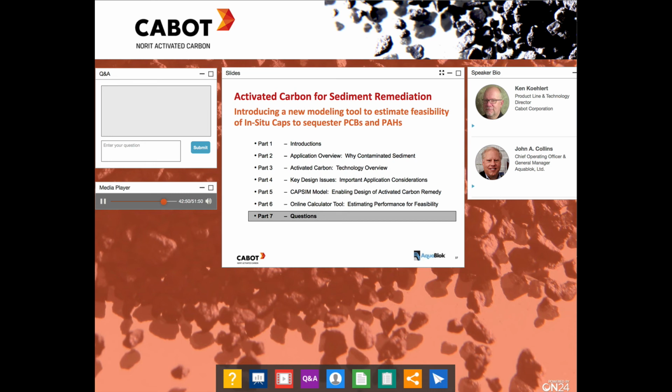Okay, we've got a question here from Karen about DOC versus NOM. So typically we measure DOC concentrations in pore water. How does the 25 milligrams per liter threshold for NOM, which we typically do not measure, compare to DOC? Well, we don't have, I think, a comparable measurement. We've used a standard NOM material from the Suwannee River. That does have some insoluble matter in it, so I'm sorry I don't have the breakdown between soluble and insoluble.